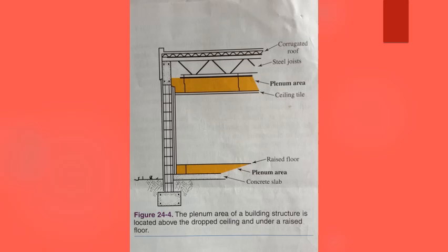Fumes produced if this covering were to burn in a fire can be dangerous to personnel in the building. In many buildings, the plenum area also contains the air conditioning system. This ducting would make fumes and vapors present in the plenum area harmful to personnel throughout the building.